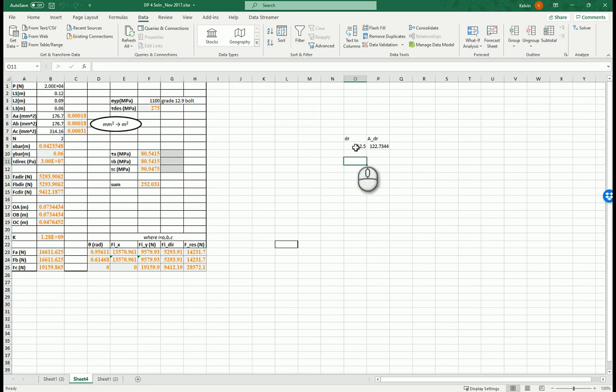So you need to actually put it in an equation in the Excel sheet. And then you do pi dr squared on 4 to get your area. So this here would be your maximum area permissible. Anything beyond this, we'll be violating the 1.5 dr rule.